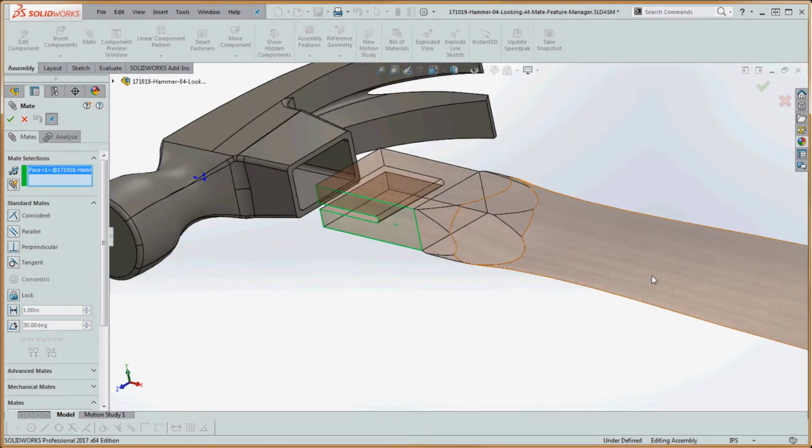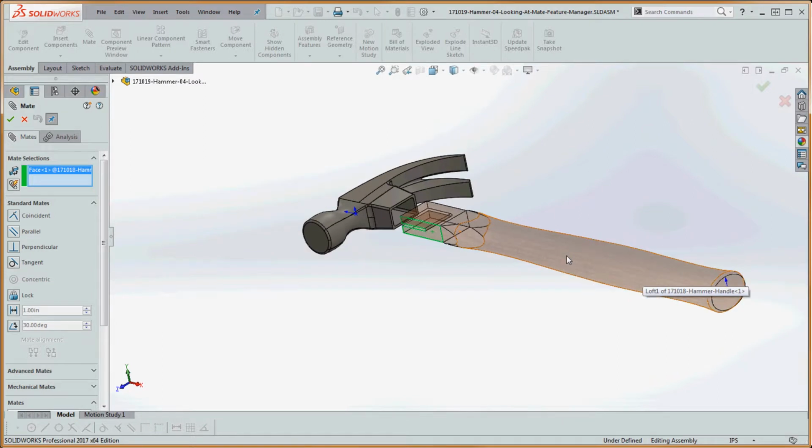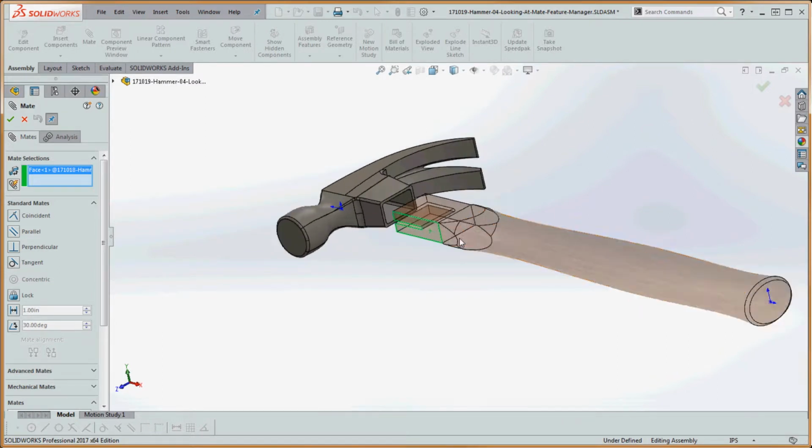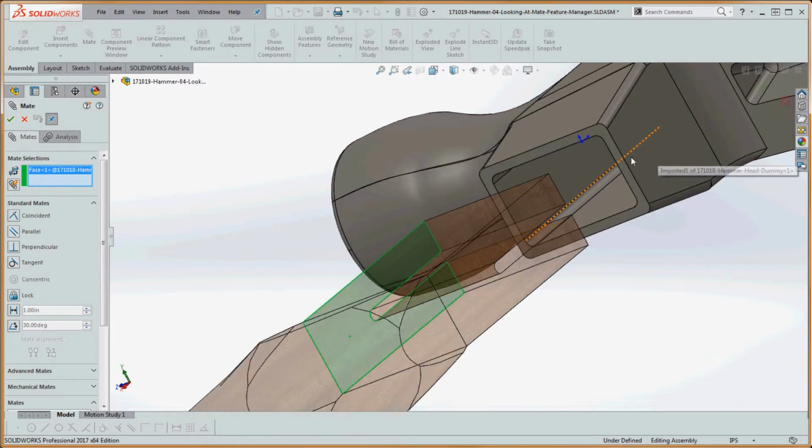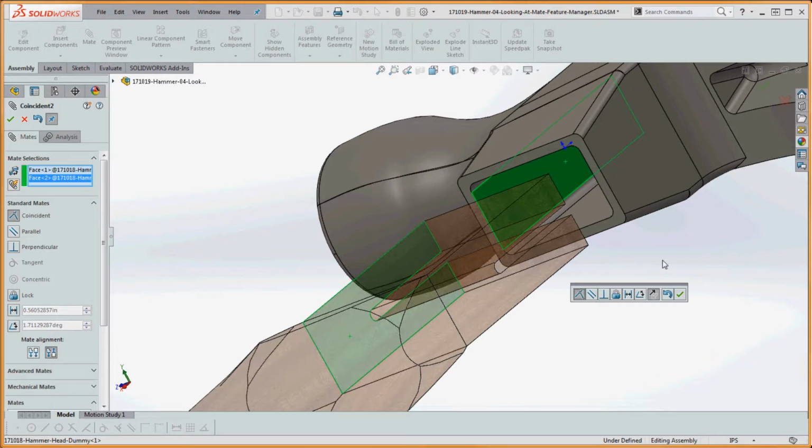And I like this feature where the fixed elements or the fully defined elements in the background get transparent, but the item that we actually want to create that relationship with remains solid, so we can actually see through it and see in much better context what we're going to be doing here. So now we have a couple different choices. We can go over here to our properties manager over here, and go through some of the selections down here, including coincident, parallel, perpendicular.